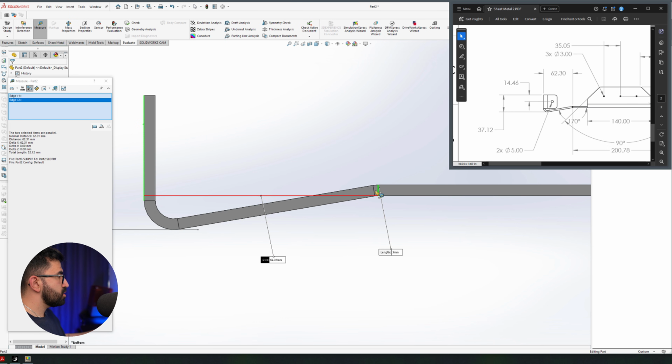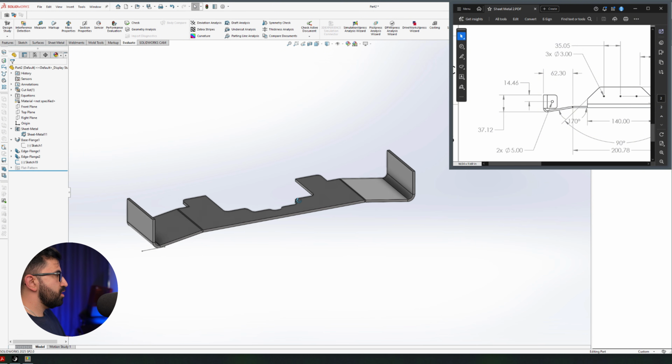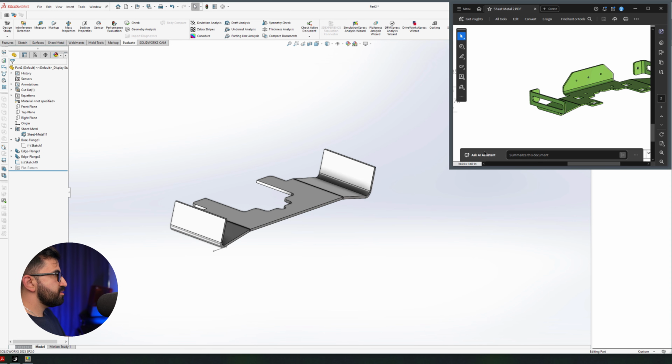This line to this line, 6231. I'll take it, okay? Because the tolerance that I have on the sheet is 200 microns, and this means 10 microns. So I'm still within the tolerance. That's number one. Number two is these flaps, these flanges on this side, and I need to add a tab.